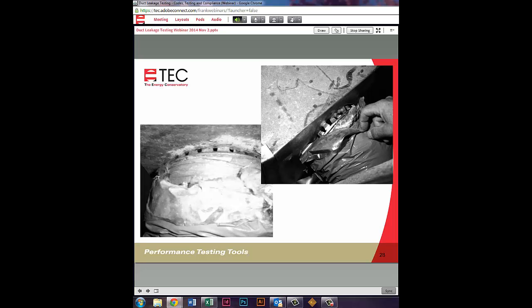So when we're talking about duct leakage, here's a couple of perfect examples where we have a plenum or a branch, and there's a takeoff attached to that. In the process of putting the takeoff into the piece of flat sheet metal, there are a number of tabs or ears, and when it's placed up against the hole in the plenum, the contractor reaches inside and basically presses down each one of those tabs.